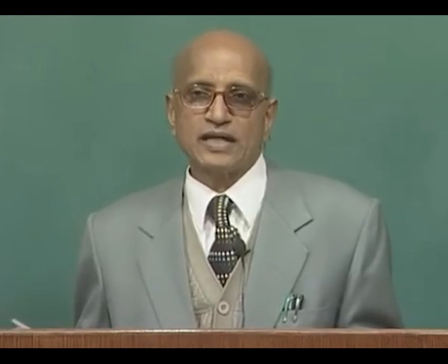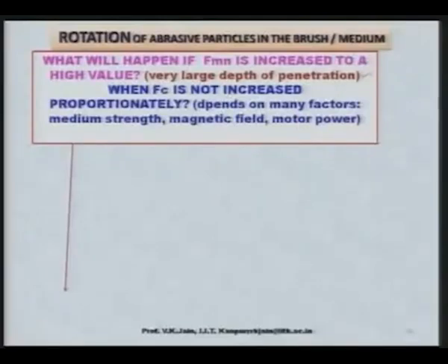Now, due to the very large depth of penetration from the high normal magnetic force, if the cutting force does not increase proportionately, then the resistance offered by the workpiece material will be much higher than the cutting force being applied through the rotation of the flexible magnetic abrasive brush, and this rotation is attained through an electric motor. So, it depends on many factors such as medium strength, magnetic field, motor power, etc.